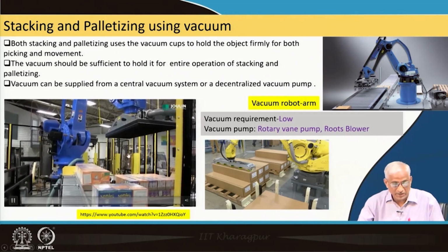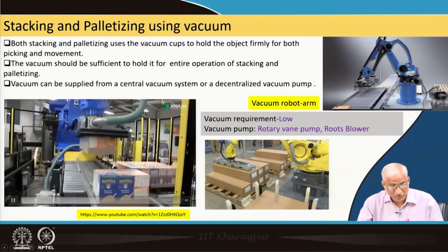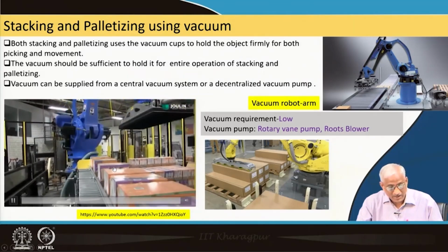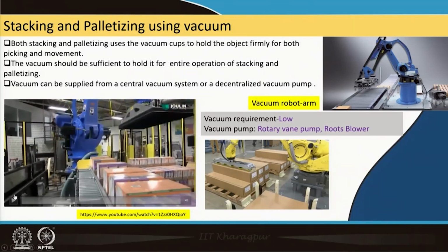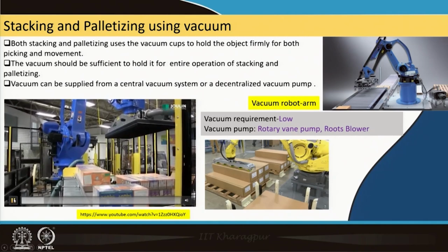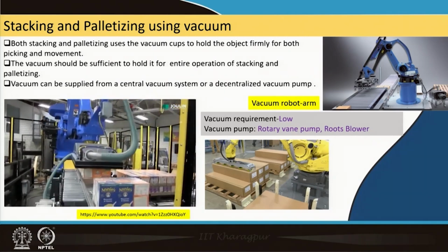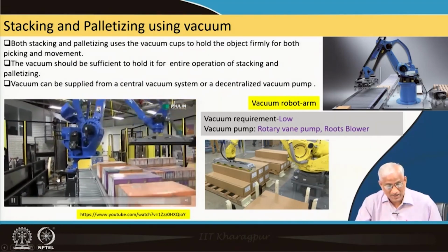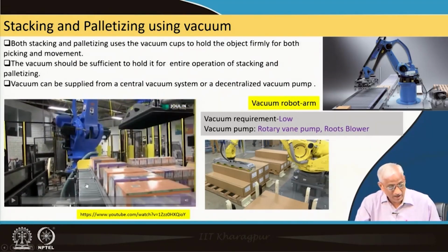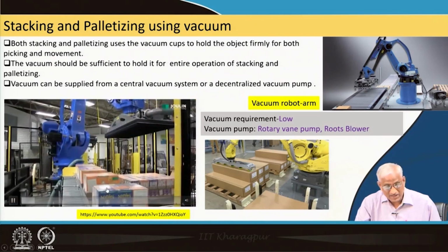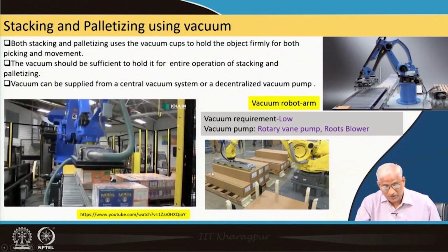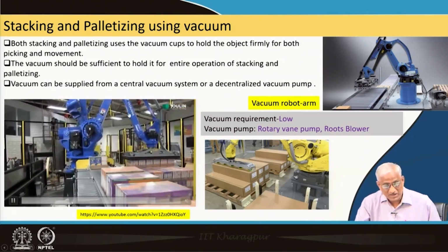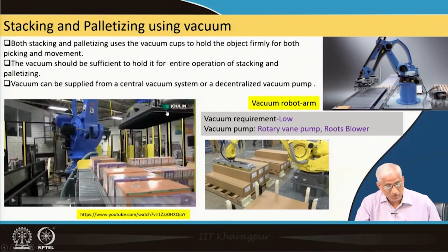See, now things are coming up, and then vacuum suction is there, and it picks this product nicely because of pressure difference, lifts it, nothing will fall because of P2 minus P1 into area, and turns it back here and stacks it here nicely. So, this way precise picking, stacking, everything is done using a vacuum suction hood.